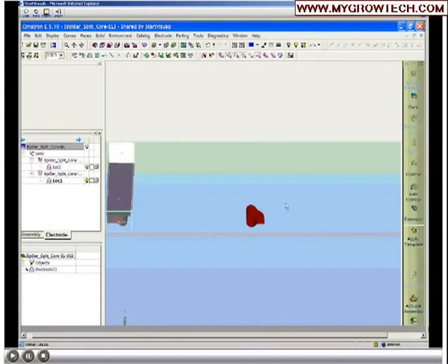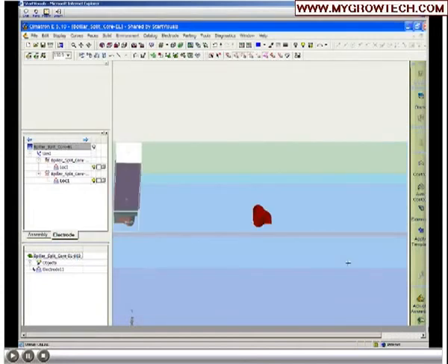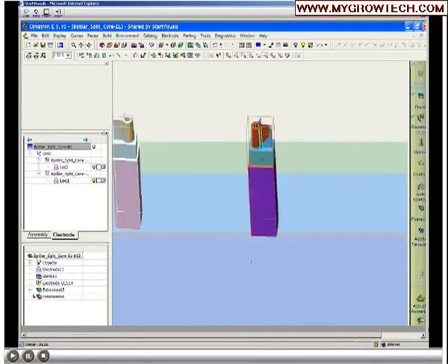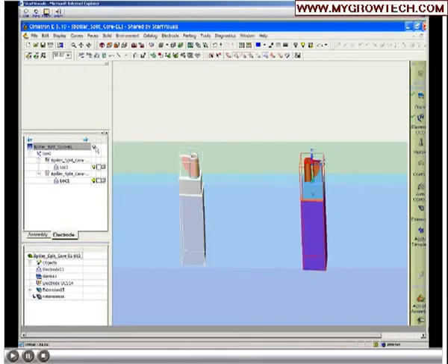Working with this one, zoom out a bit, we will apply a template. Here's the template we just made with a nice pretty picture to remind us of what we did. And it applies the exact same analogy as the first electrode. So with a library of templates, it can be very easy to quickly automate different styles, different ways that you may create those extensions, different sizes that you may use.